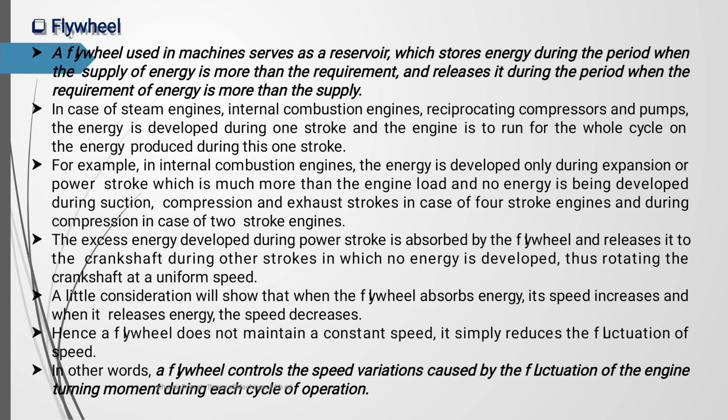So in the case of steam engines, internal combustion engines, reciprocating compressors and pumps, the energy is developed during one stroke, and the engine is to run for the whole cycle on the energy produced during this one stroke. In the case of a steam engine, the flywheel works like that. For example, in internal combustion engines, the energy is developed only during the expansion or power stroke.